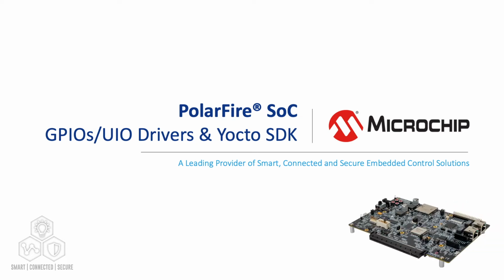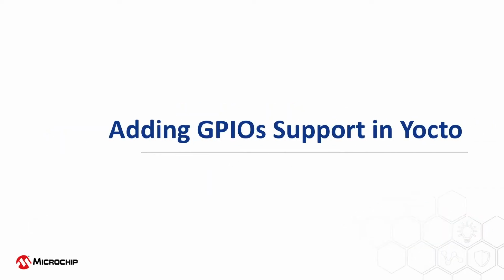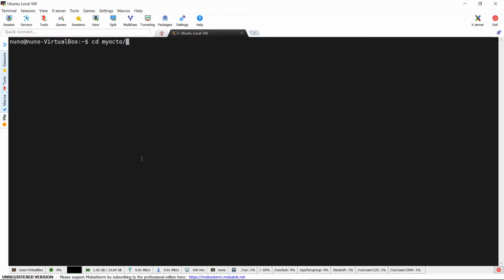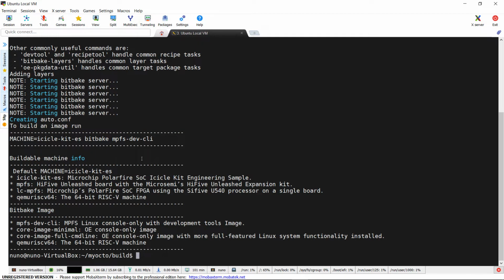In this video, we will explain how to enable GPIO support in Linux with Yocto and use a proper driver to control GPIOs. In order to enable GPIO support, we have to reopen Linux menu config with Yocto. Let's go to our Yocto folder where we previously built the development image and launch the setup script.